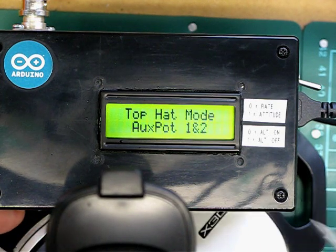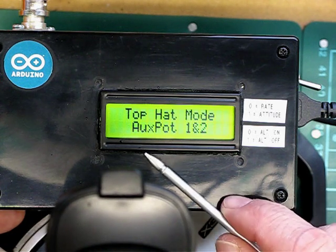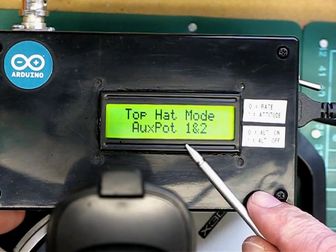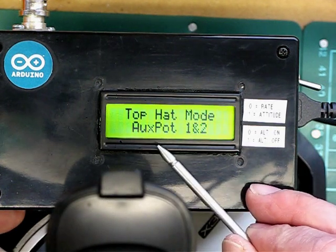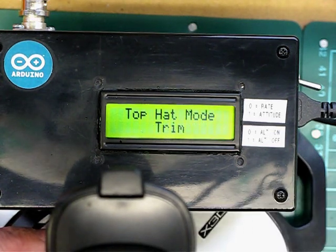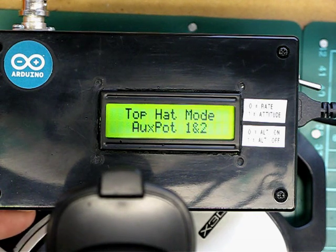Next is the top hat mode on the joystick. It's currently set to aux pot 1 and 2, so basically if I move the top hat on the joystick it will affect the auxiliary analog outputs 1 and 2, but you can change that to trim mode, so basically it will trim the elevator and the ailerons, so you can switch between the two modes for the top hat itself.